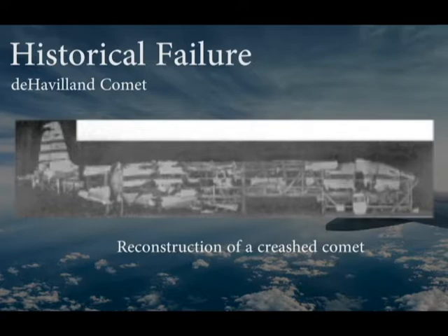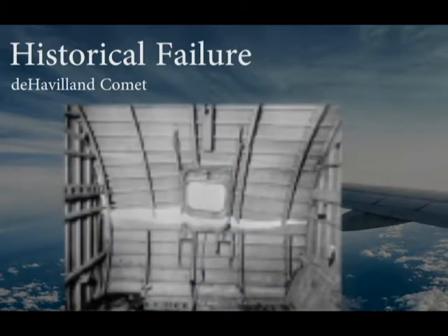To determine the cause of the crashes, an entire fuselage was placed in a specially designed tank, and the fuselage was pressurized with water to approximate flight pressure conditions. The pressure was then cycled to simulate the lifespan of the aircraft. After about 3,000 pressurization cycles, including the preceding flights taken before the tank tests, the fuselage failed. Upon the examination of the failed fuselage, it was determined that the failure originated at one of the windows.